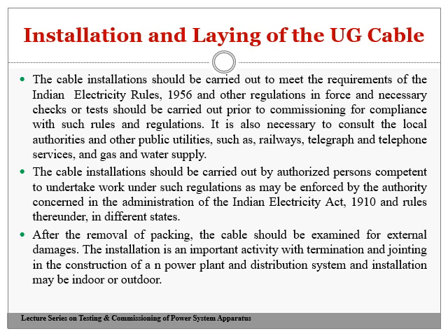That is, not only must the procedure follow the Indian Electricity Rules, but any regulation related to checking and testing of the cables should be followed before commissioning, or charging the cable. It is also necessary to consult the local authorities. This is almost essential.